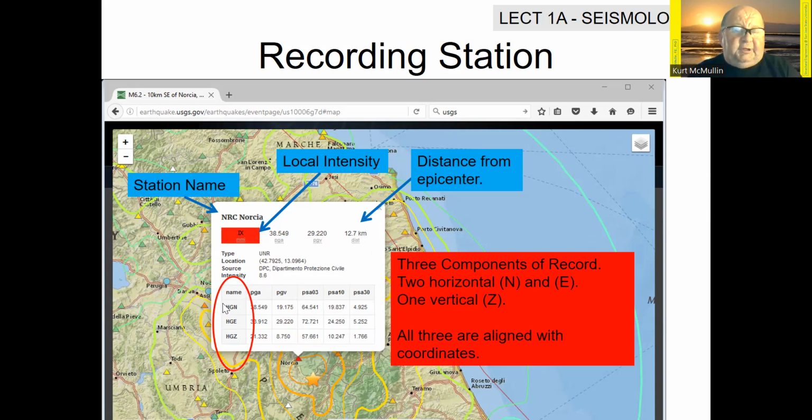And then we usually get 3 different readings of the 3 different components of that earthquake motion. The instrument measures acceleration along a line. Usually these instruments are built so that they measure 3 different axes, including vertical, of how that instrument moved. So usually we get 2 horizontal readings, maybe a north-south and an east-west, and we get 1 vertical reading, maybe defined as the z-axis.